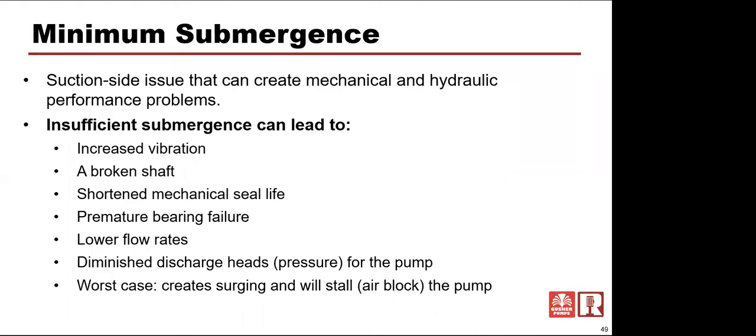Sometimes we'll angle cut that pipe on the bottom because by angle cutting it on, let's say, a 45-degree angle, we're creating a larger apparent intake of that pipe, and therefore a lower velocity, because the pipe size appears to be bigger to the pump. You'll see a lot of times vertical pumps have a bell intake on them. And again, it's trying to reduce the apparent velocity at the edge of that pipe to prevent drawing air down into that pump vortex.